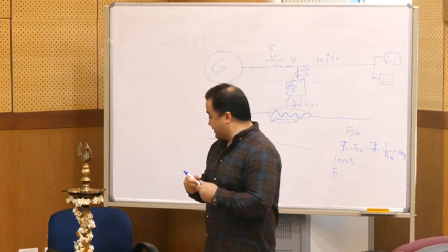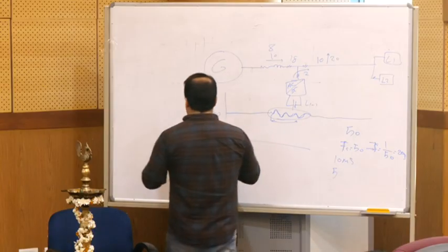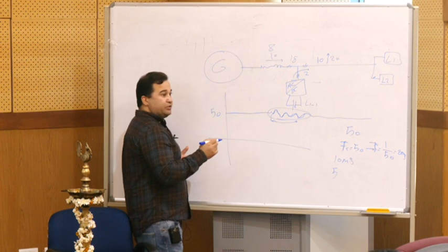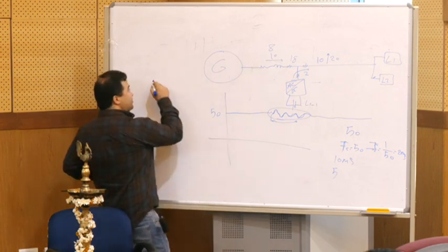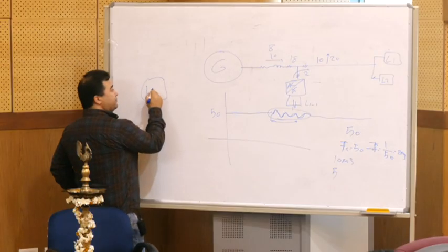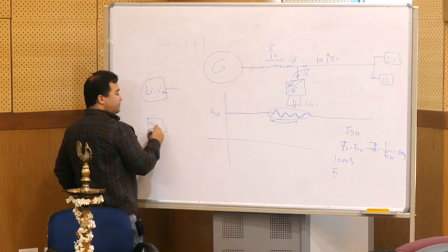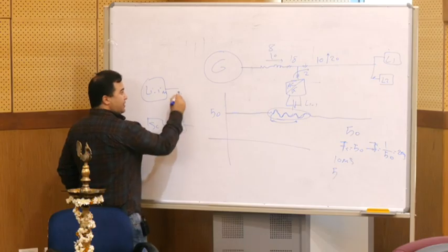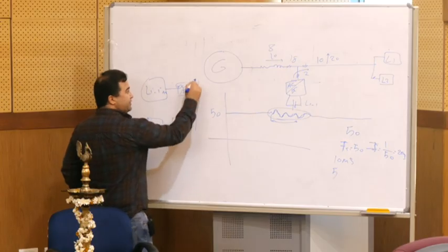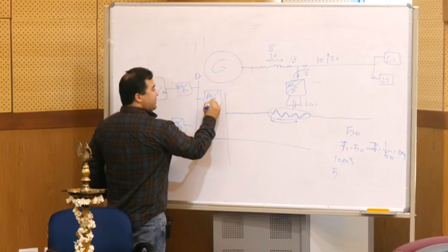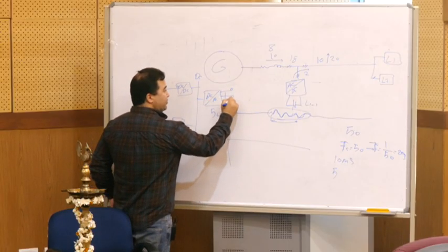So for this case, they use a hybrid energy storage, a combination of high power and high energy technologies. It's like this one. We use the lithium-ion, and then we use the supercapacitor. We have a DC-DC converter, and another DC-DC converter. So we provide the DC bus here, and based on that, we have a DC-AC converter and provide the grid voltage here.